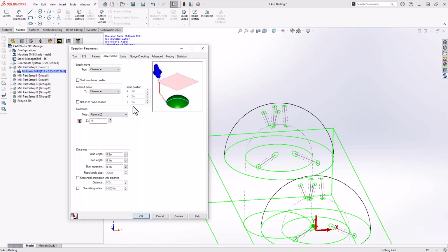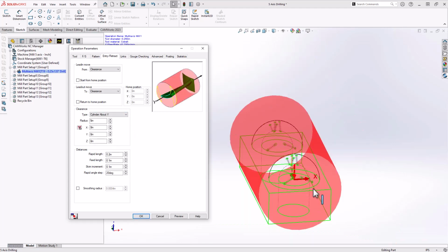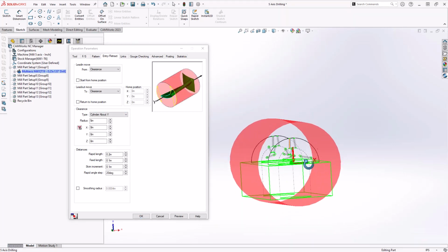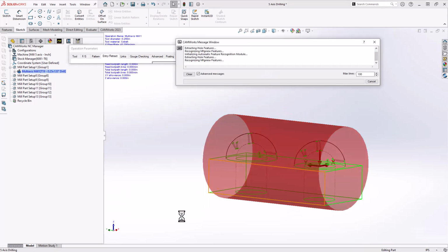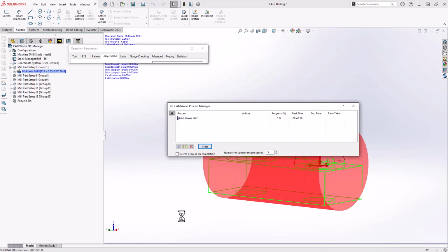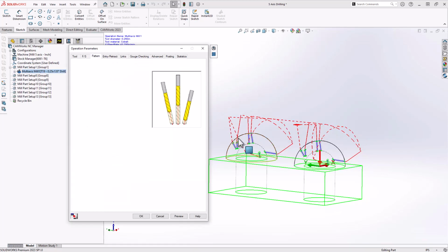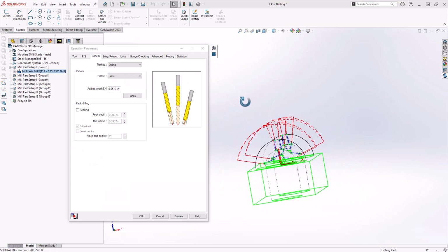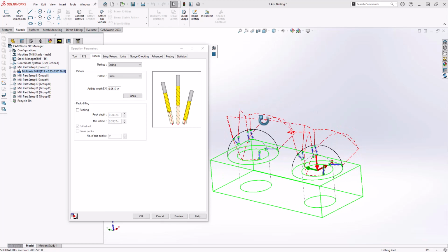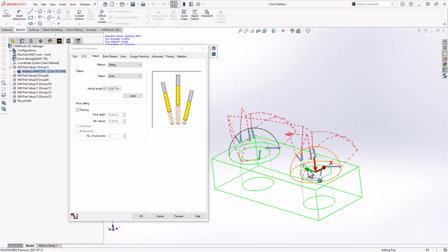In my case here, I'm going to take advantage of my multi-axis mill clearance abilities, and I'll say let's do a clearance about the y-axis so I can clear to a cylinder. We'll do a preview on that. And now we'll see that we have a toolpath that does all of the lines on my part, and all I had to do is define the first 3 and then do some mirroring and some translations in my 3D sketch.